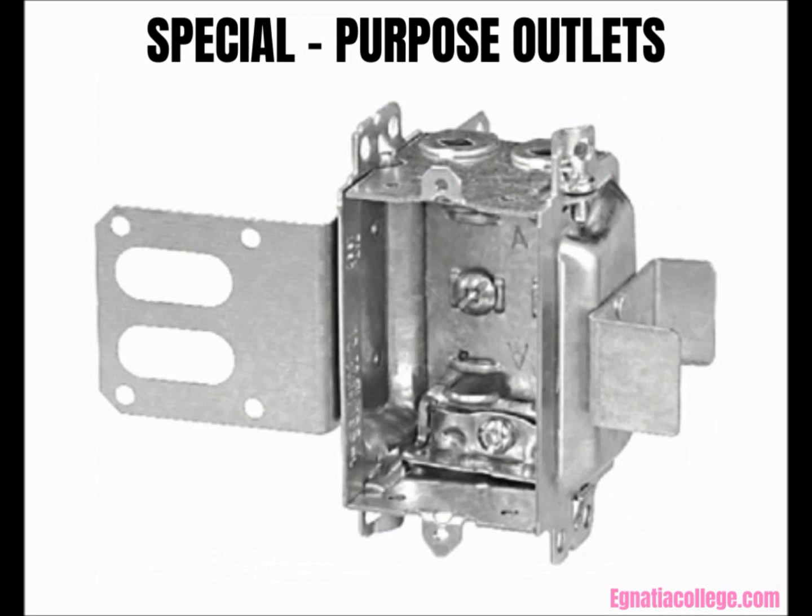Special purpose outlets. Special purpose outlets are normally shown on floor plans. They are described by a notation and are also detailed in the specifications. The plans included with this textbook indicate special purpose outlets by a triangle inside a circle with a subscript letter. In some cases, a subscript number is added to the letter.